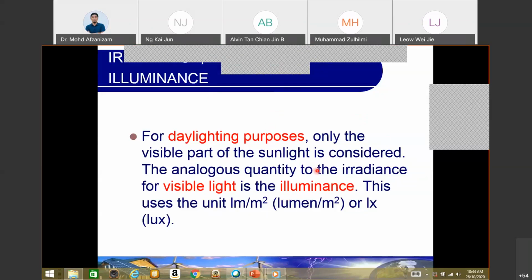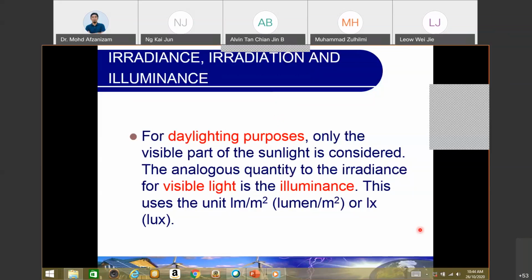Some activities refer to a specific lux. For reading, it is recommended to have 300 lux. For your toilet, it might be 100 or 200 lux. That's the approach of energy management actually. So do not turn everything on, which wastes energy. The higher the lux, the higher the energy you consume, which leads to higher bills on a monthly basis.